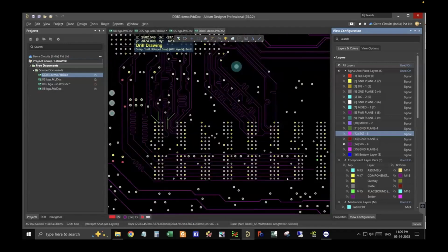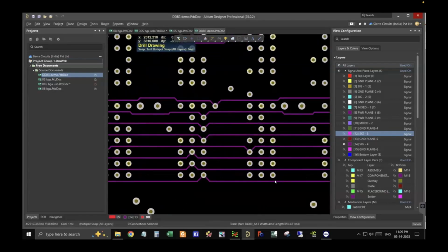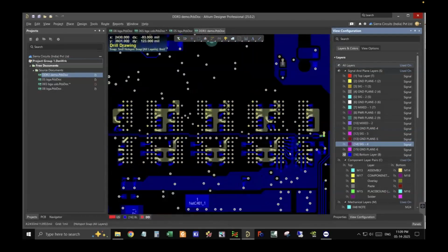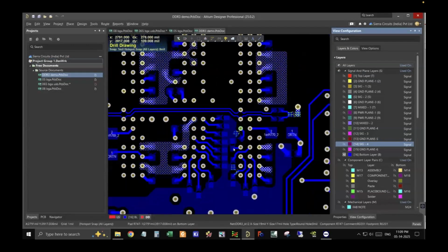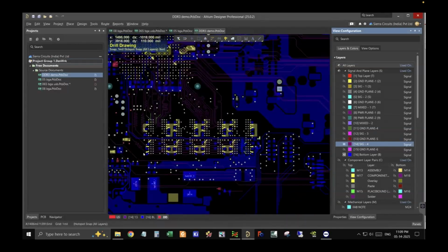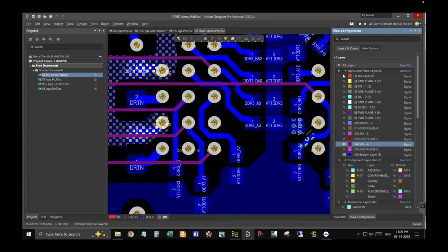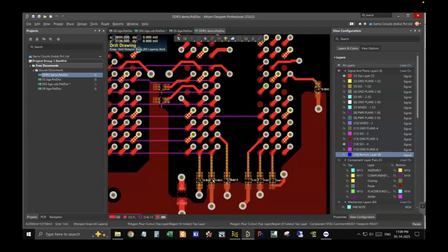So now all the address lines and the control lines are routed over here. Coming to the termination resistor placement: all the termination resistors are placed at the very end of the daisy chain. As you can see, the chain is coming all the way till the end, on the right-hand side. At the end over here, on the top and bottom, we have placed all the termination resistors. These are our termination resistors over here, and on the bottom layer, this one.